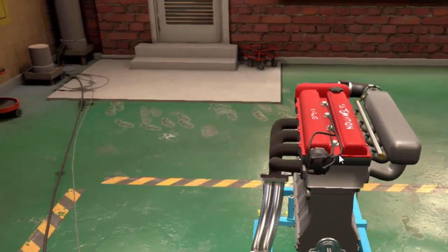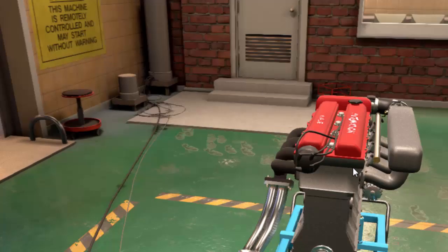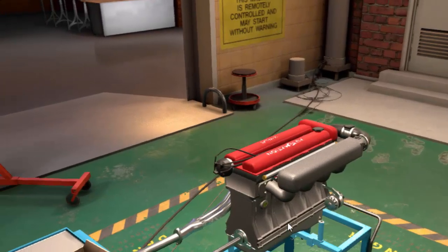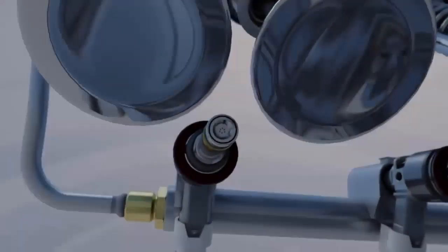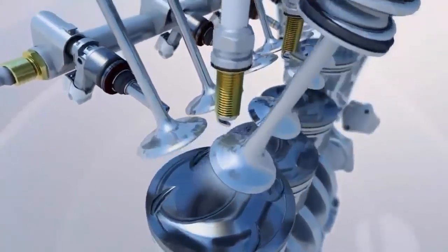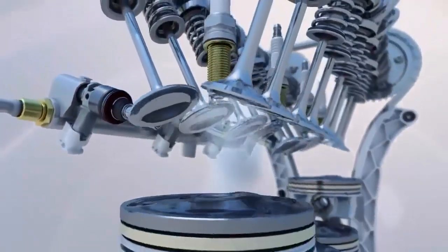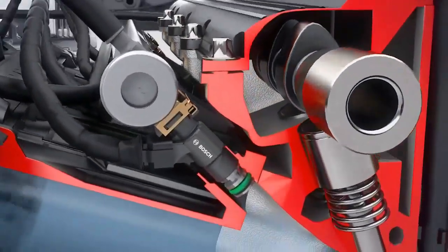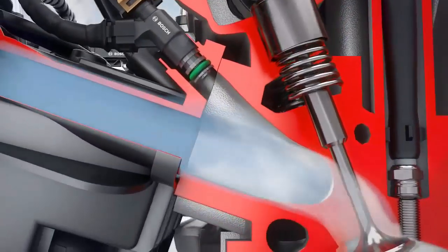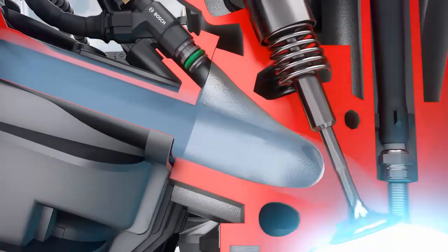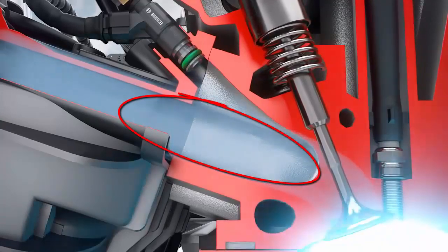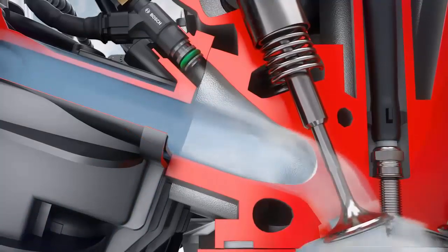That is, in systems where there is no fuel pressure sensor, not to be confused with a pressure regulator, the control unit does not know the value of the real fuel pressure, it only knows what is in its program. That is why it is so important to measure fuel pressure during diagnosis. After all, if the nozzles open for the same time and the pressure is higher, then more fuel will come into the cylinders in the same time. And this is already a rich mixture.